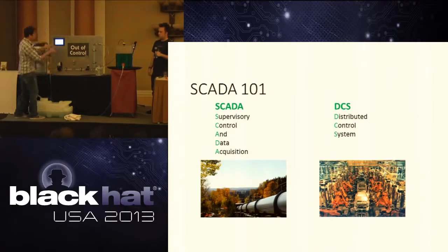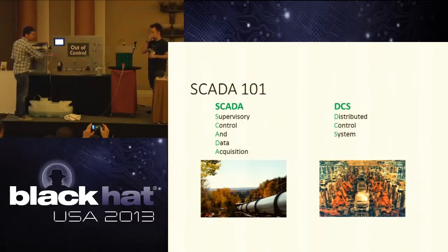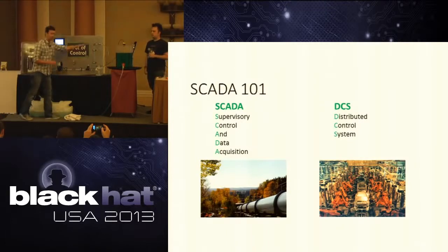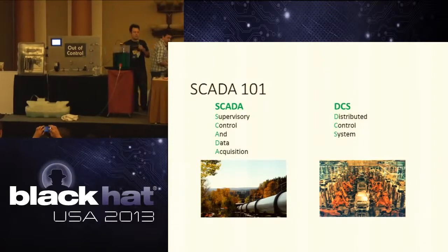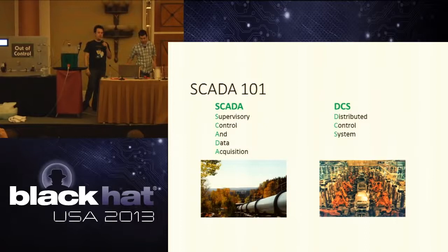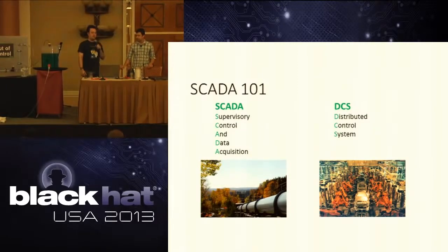We go through, and we're starting to pump, and our level's starting to go up. But what we'll end up seeing is, from the human-machine interface, I shut off this valve, and then the pump turns off. So this is all implemented in logic inside of here. And we can show a little bit later what happens when we raise the level of the tank itself. Yeah, it's just going to automatically shut off the pump once the level is reached to be full.